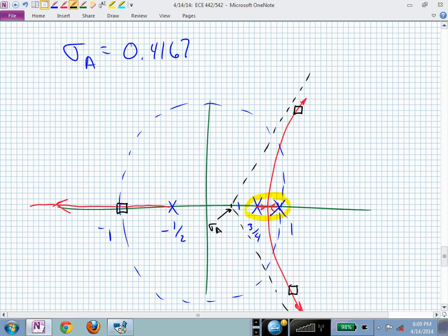And that gain may be too big. Those that were near 1 have already zipped outside the unit circle. Meaning, we may want to back off on the gain from a value of 0.875 down to a value that gets you to those triangles right here where your root locus just intersects the unit circle.